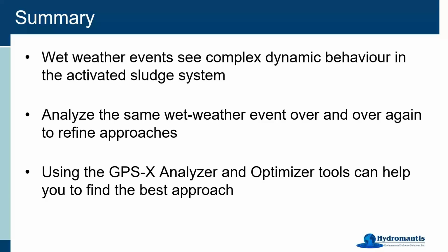To sum up all of that, wastewater treatment plants see really complex dynamic behavior when a wet weather event goes through them. There's obviously a lot of stress on the system as the load is increased, but even dropping off the load really quickly can cause a lot of dynamic things to happen in that system as well. What we'd like to be able to do with a simulator is analyze that same wet weather event over and over again, refine the approach, learn what the system is supposed to be able to do, and use tools like the analyzer and optimizer in GPSX to help find that optimized approach.